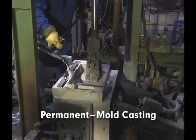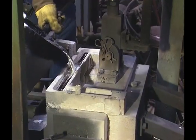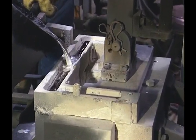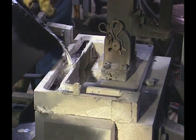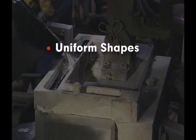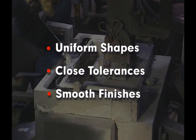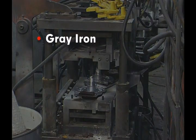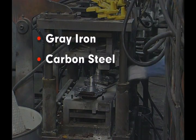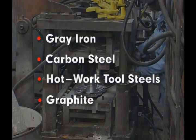Permanent mold casting is a semi-precision process, which, because of the chilling effect of the molds, can provide superior mechanical properties. In addition, permanent mold casting can produce uniform shapes, close tolerances, and smooth finishes. Permanent molds are usually made of gray iron, carbon steel, hot work tool steels, or graphite.